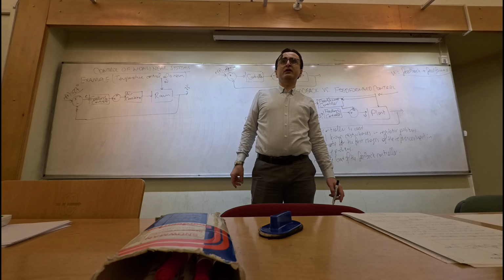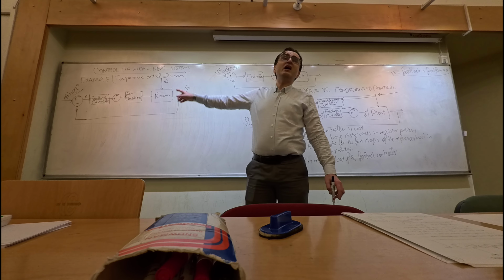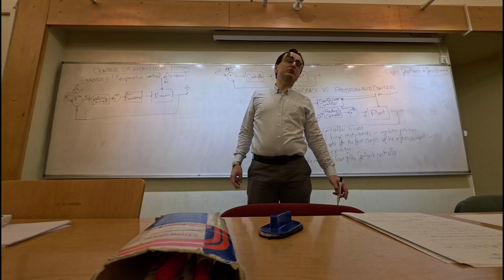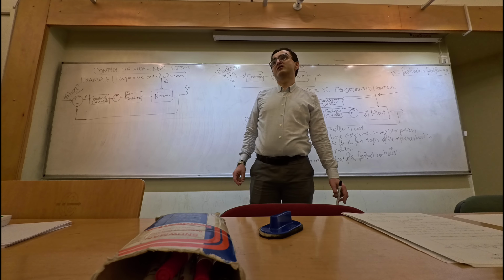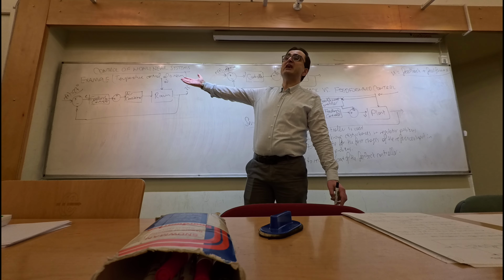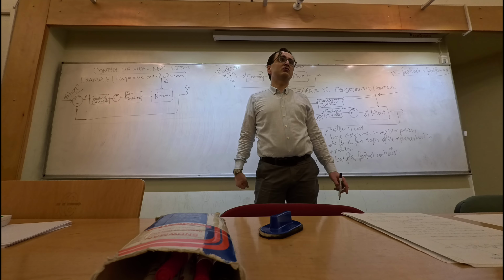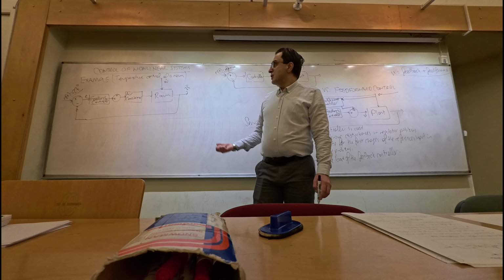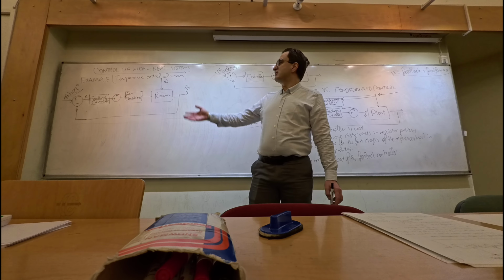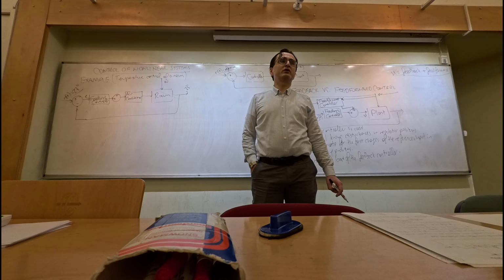But what is important here is that for the feedback controller to be able to work, we need an error to appear first. Without the appearance of the error signal, the feedback controller is not working here. So the system temperature should deviate, maybe significantly, from the reference signal before a feedback controller can actually take action. So how can we avoid this? How can we make that error signal smaller before a feedback controller starts working?